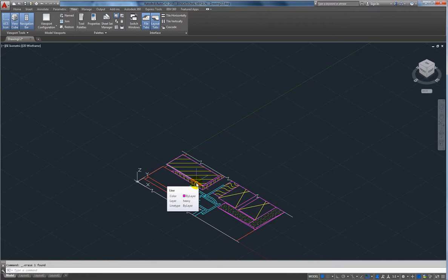So I think it's important to understand these concepts. If we're going to start working in 3D, Z becomes important. For AutoCAD, XY typically always represents the ground. That plane represents what's happening at the ground, and then Z represents what's coming out.